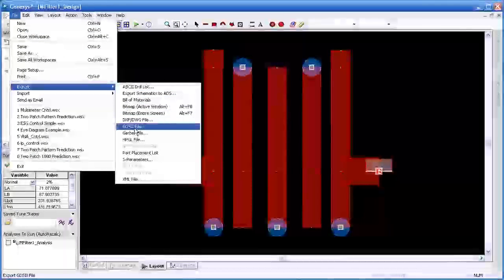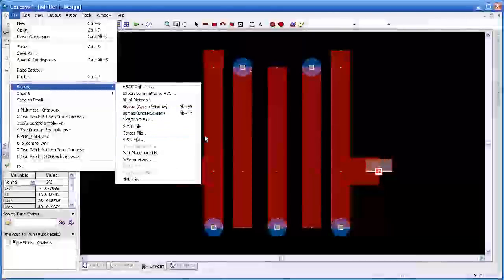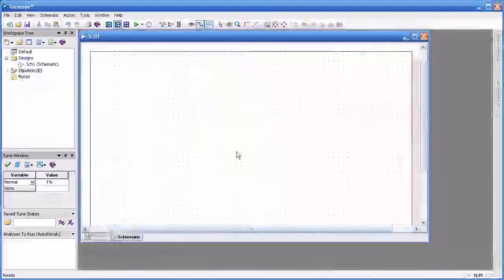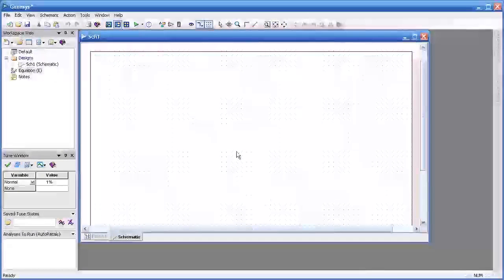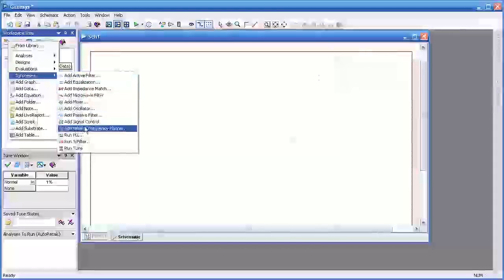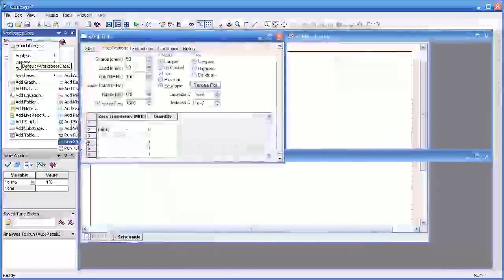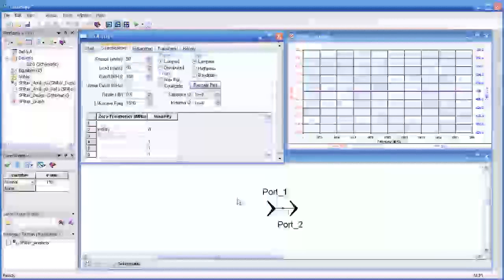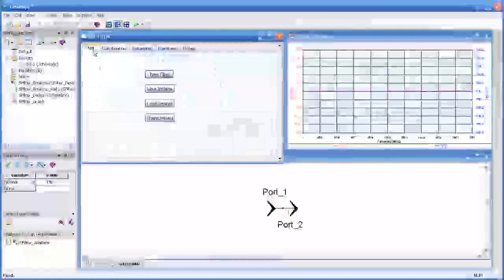And we can select a number of methods, GDS2 or Gerber, DXF, or whatever. Lastly, we will look at the S-Filter tool. S-Filter offers the additional capability to set zeros of transmission, add transforms like Norton and Kuroda, and filters may be realized as lumped or distributed equivalents. If we go to the workspace tree and select Run S-Filter, here you see the dialog for S-Filter and the specifications page.